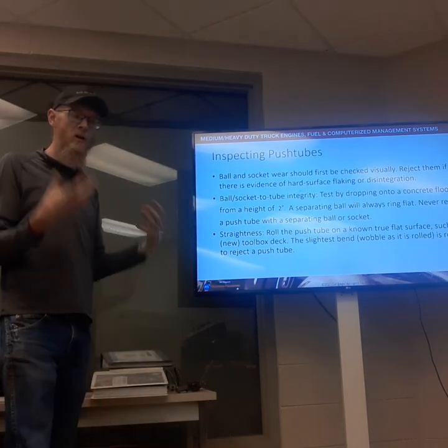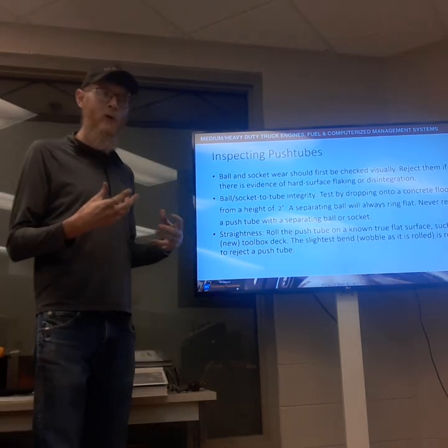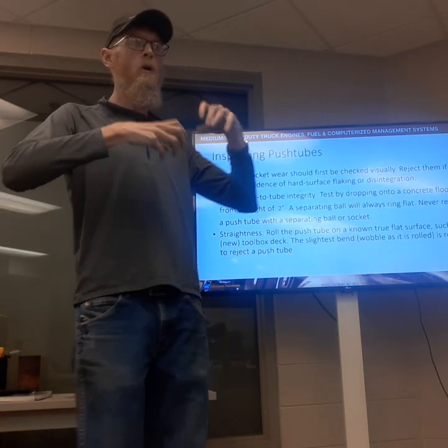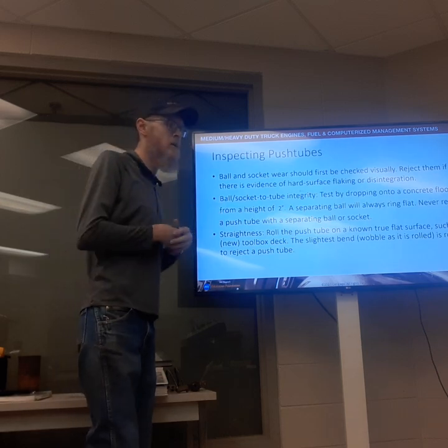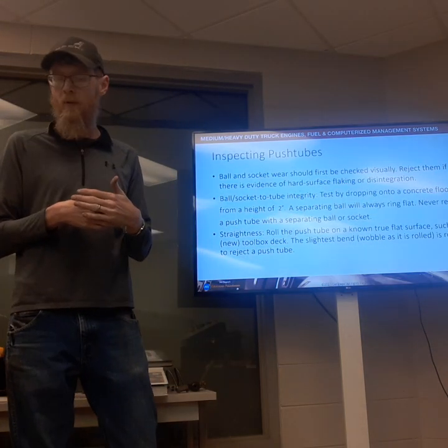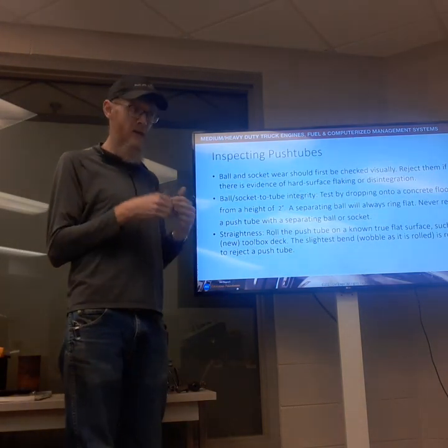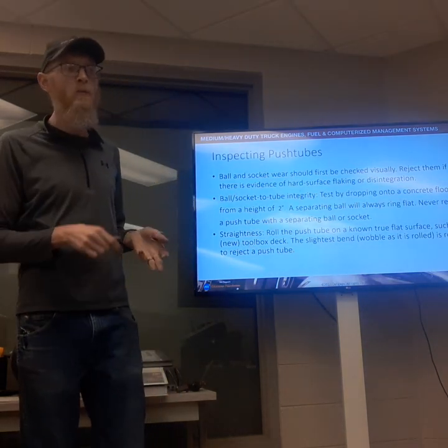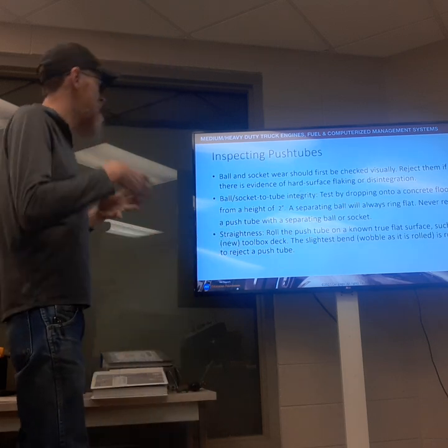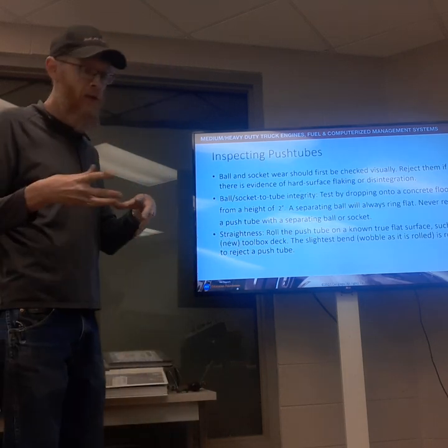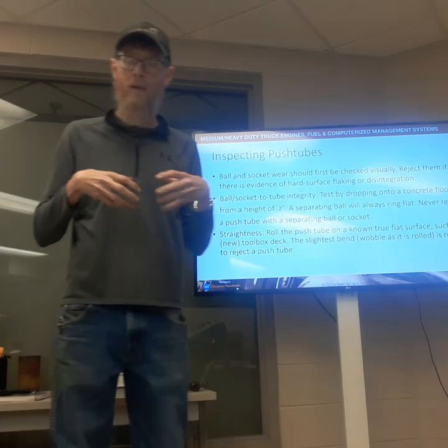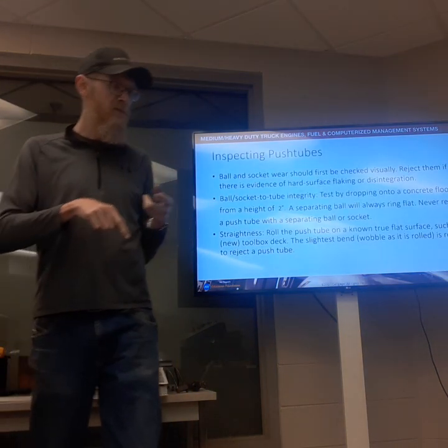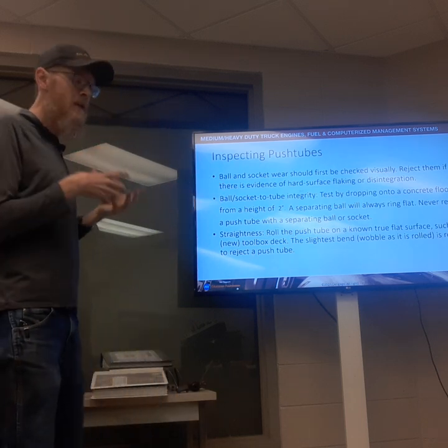And when we go to start up the engine, it takes a moment for our lube oil pump to pressurize our lube oil galleries and get oil distributed to all these moving parts. So briefly, on startup is where we're going to get this wear between our rocker arms and valves, between our camshaft lobe and the cam followers. All these places are things that we should be looking at and inspecting, making sure there's no surface damage to the cam lobe, the valve stems, any of these parts.